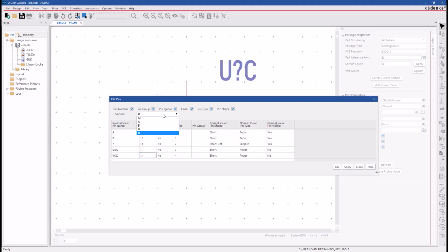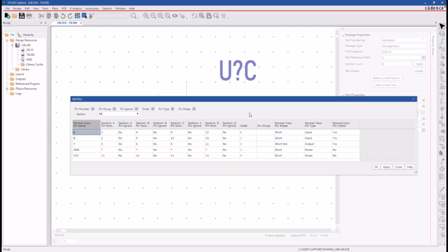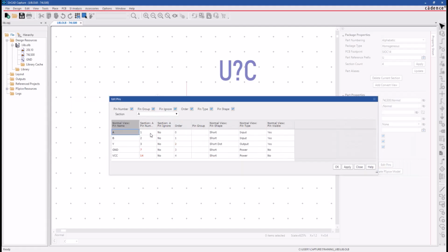There is one more column called Pin Group. This property allows you to swap the pins without changing the behavior of the output. This means that pin names A and B or pin numbers 1 and 2 on the gate are equivalent inputs. The pin group property is a common value across both pins. When the pin group property value is set to the same value for these 2 pins, that tells the PCB editor that you have a swappable pin gate.